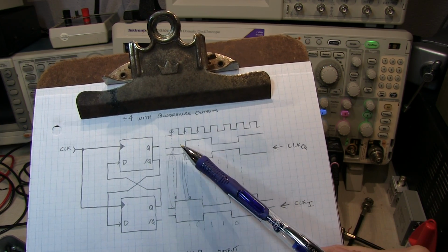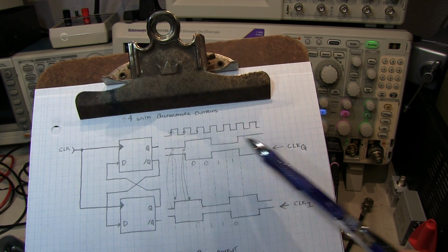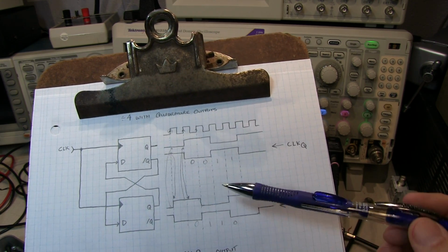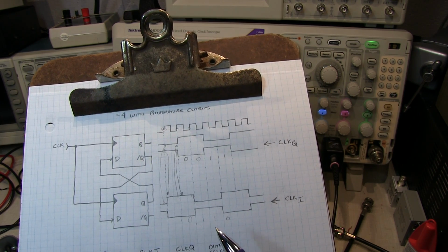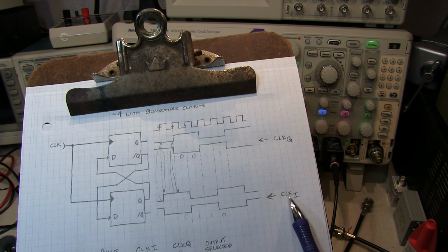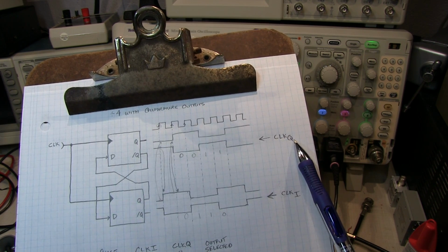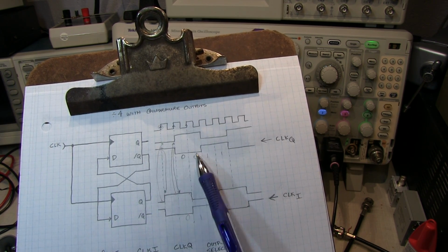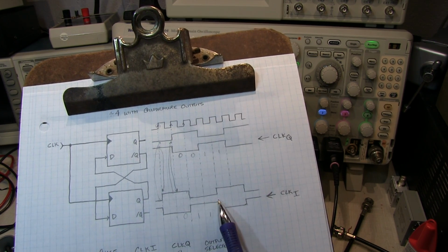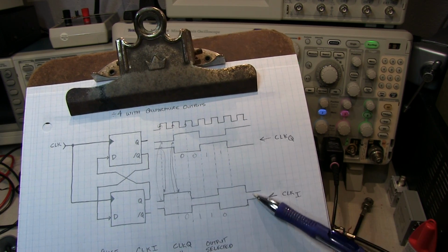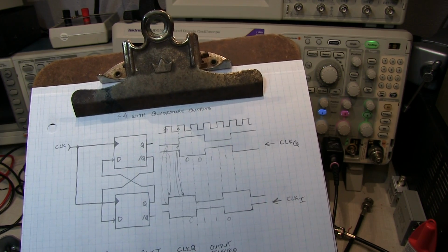So what you wind up with is a clock signal here that is 1/4 of this frequency, and the same thing down here. But if you look at these two, they are shifted by a quarter of a clock cycle. The two clocks that we're going to use in the circuit are this one, which we'll call clock I for the in-phase clock, and this one, clock Q for the quadrature clock. We can see that the quadrature clock follows by 90 degrees. Say this edge is 0, then that edge goes a quarter of a cycle later, then this comes down and that comes down. So there are our quadrature clocks and how they're generated in the flip-flops.